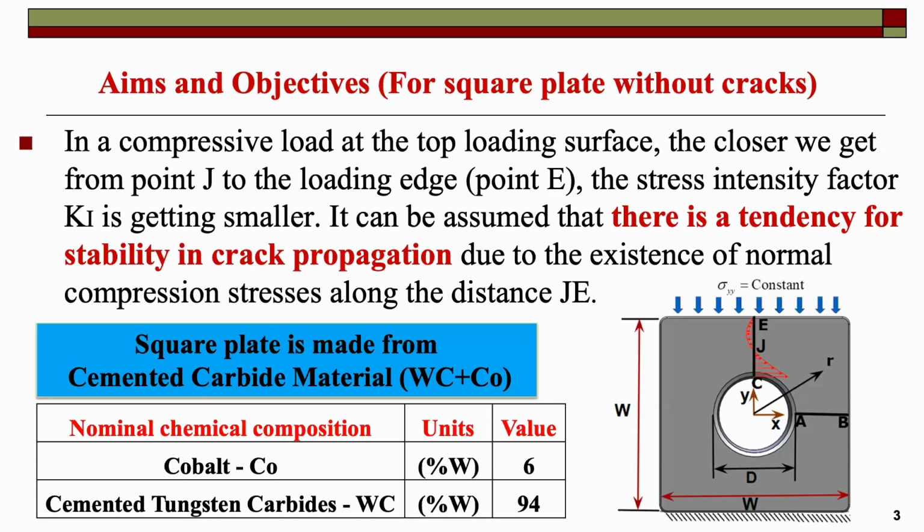Here we get tension, and at the upper load we get compression. So you transfer from tension to compression in normal stress, because there is no shear on the vertical and horizontal symmetrical planes. So the normal stress is the principal stress, okay?